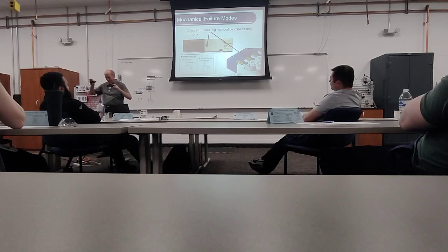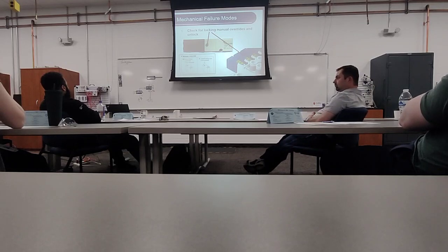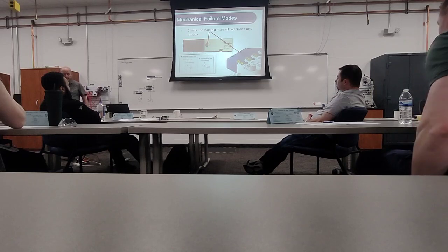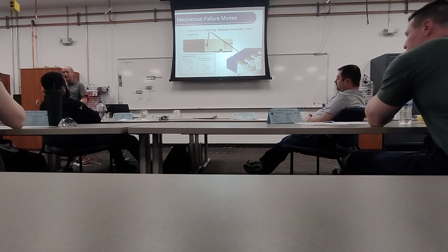So let's say that my controls are here and the machine's on the other side of that wall. I can flip the switch over there, walk around the wall, and when I get there, I find out that Chloe was standing in the machine and I hit her with an actuator. Now I'm gonna have to run. It's gonna be a problem here, right? I like this one because if I cannot see what I'm moving, I need to be on the radio with somebody. I need somebody's eyes on what I'm getting ready to do, saying stop, you're moving the wrong one. I need somebody looking at this.